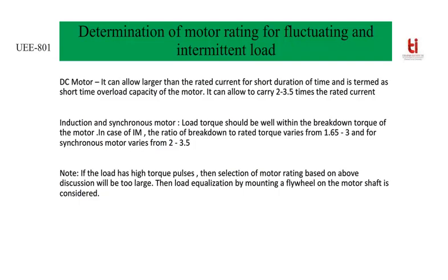At the same time, it should also be noted that if the ripple across the load is too much, that means the peak to peak difference is large, so that for some duration the load is very high and then reduced, this approximate method is not suitable. In that case, we have to use load equalization by mounting a flywheel on the shaft of the machine to generate extra torque or to support the driving torque of the machine. So the flywheel will supply stored energy to support the developed torque to cope with the load torque.